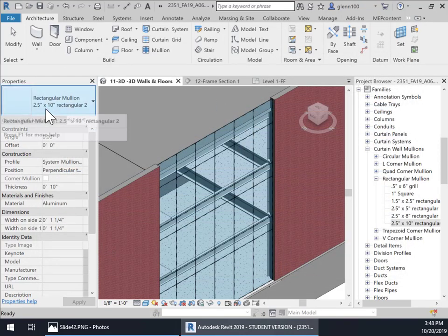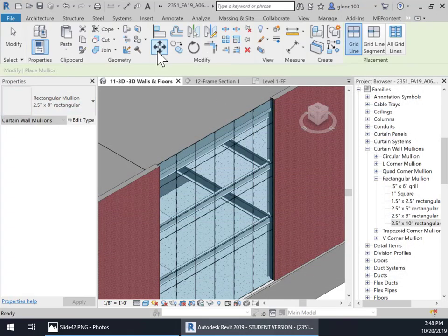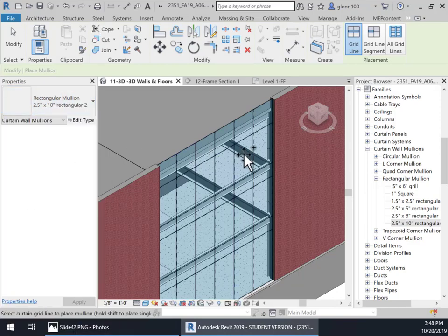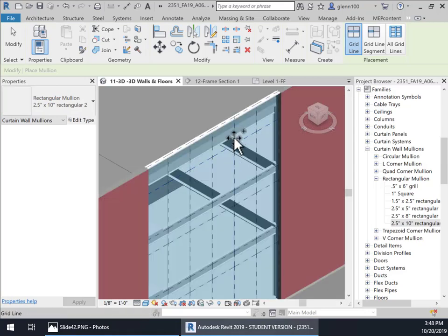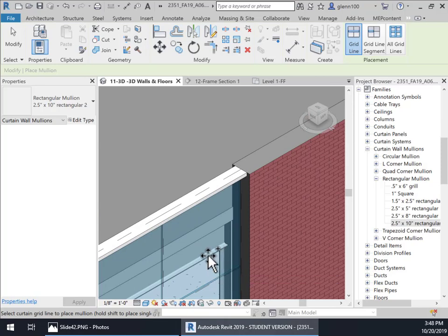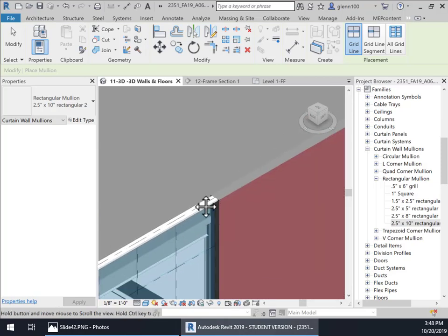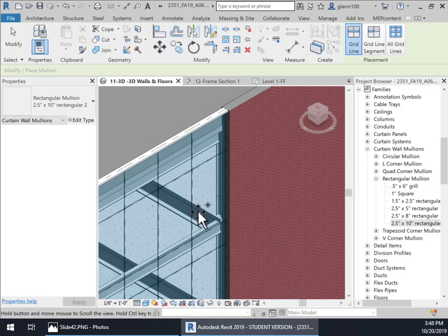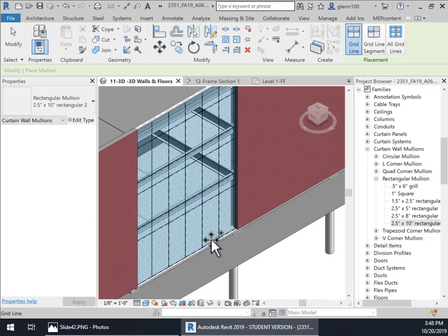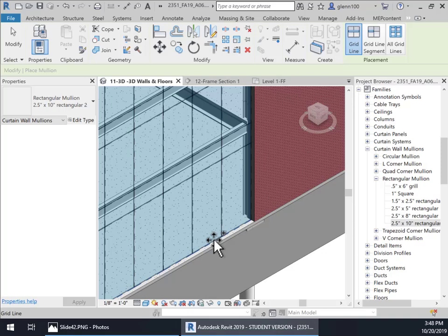And then, so we got this one up first. So we're going to go mullions, and let's select 10 right here. And we're going to just select that top line, and we're going to add a 2 by 10 mullion there. So we got our 2 by 10 mullion. Fantastic. It looks great. The other horizontal one we want is the bottom mullion to be the same width.